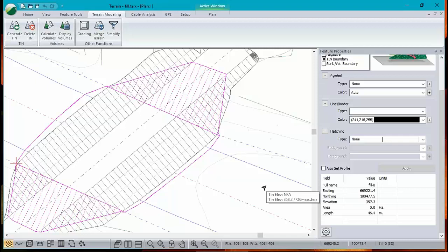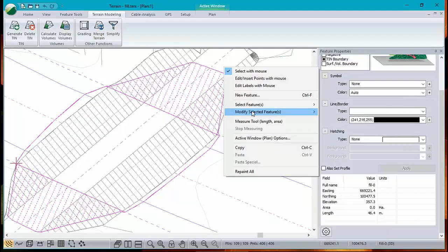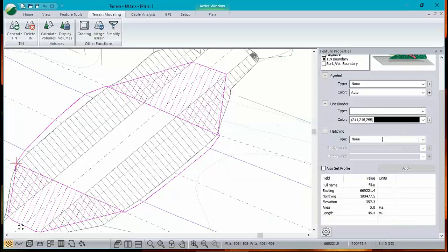In this example, I would take that culvert and figure out, first of all, what kind of culvert it's going to be, how long it's going to be. I can measure that right off of here. Let's just do that. From here over to there is 25 meters roughly. So I can do an estimate.